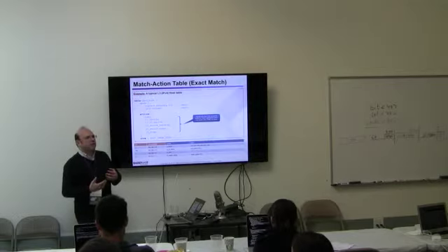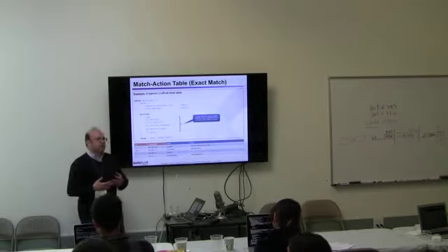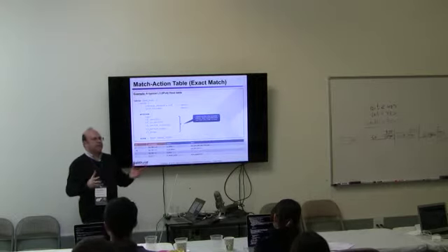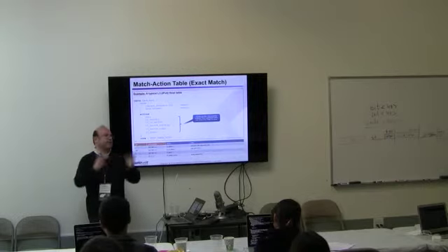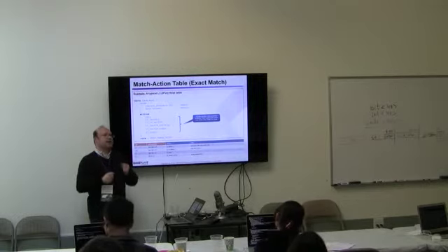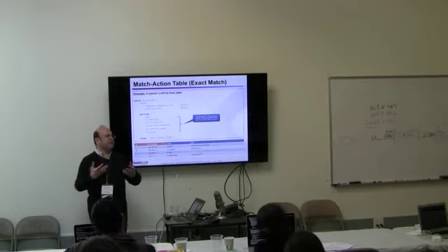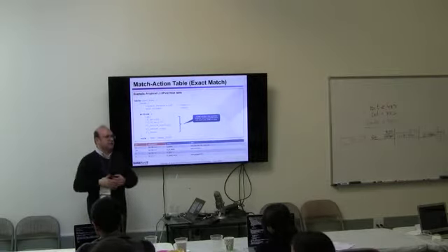In hardware, typically people don't do lists, but they use multi-way hashing or something like that. It could be one hash and then a fixed number of buckets of a fixed size. But typically they need to store the key in memory as well, so even though you did a hashing and got to the right bucket, you need to compare the actual key so that you don't mismatch, right?